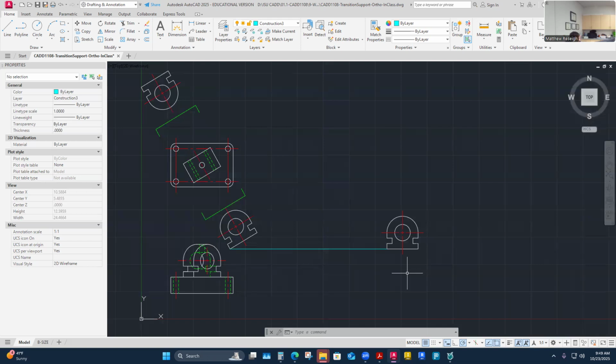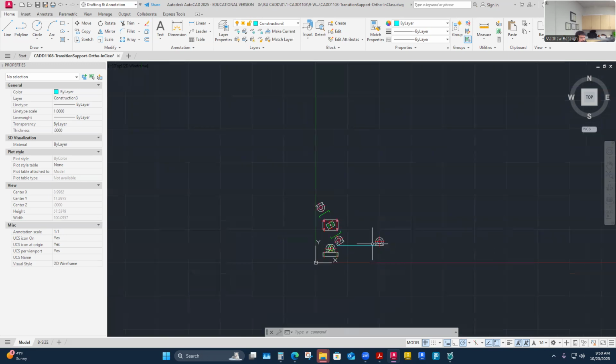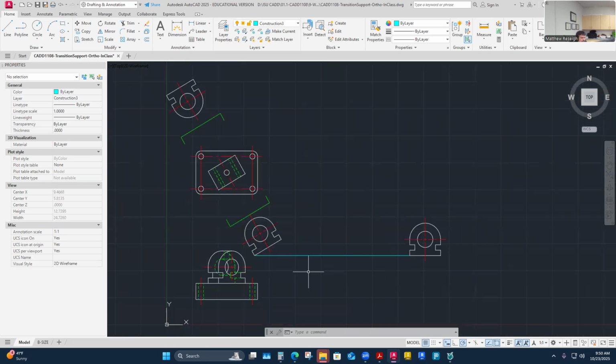We haven't done any of that yet either. But the real nature of mechanical drafting is we do a lot of detailed views, and we do a lot of detailed views that are also scaled differently than where they were pulled from, so that I can expose details and dimension stuff. And then on the same sheet where it came from, I'll have multiple scales on sheets, but of course, because of that, I need to notate in the detail view its scale if I've changed it from what the scale on the sheet says. All right. I've talked about that before, but that's me thinking ahead a little bit.